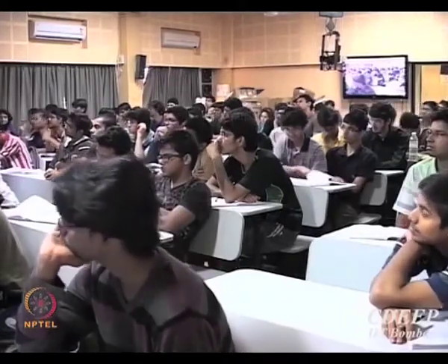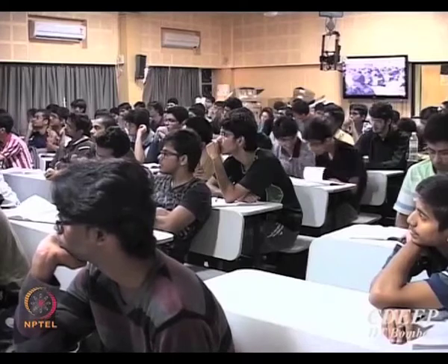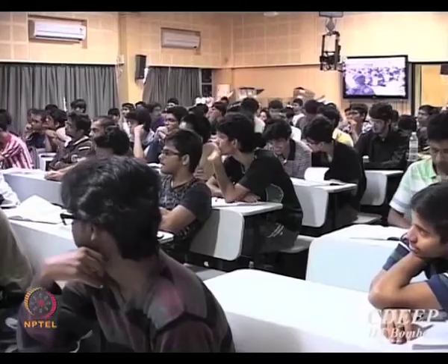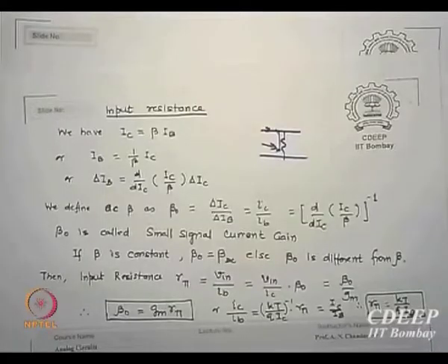What you are saying, in a way, is that during fabrication, yes, I can do something. But once I fabricate it, that's the end. That's the fixed value. Whatever dopings I used, whatever process I went through, that will be fixed for you now. I cannot do anything about that. I have fixed beta, fixed the base width, fixed the doping of the base-emitter junction, fixed the transit time, fixed the minority carrier lifetime. Everything is fixed, nothing is in my hands. Externally it is going to spoil something, but that is what the limit is. This is internally itself creating a problem.